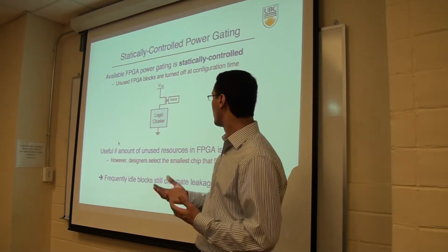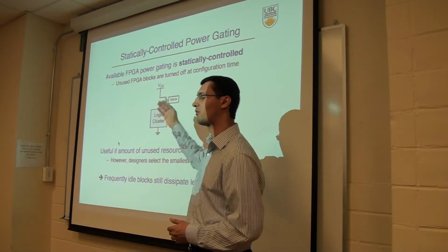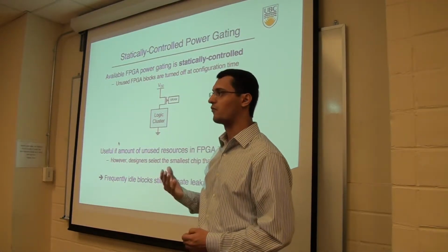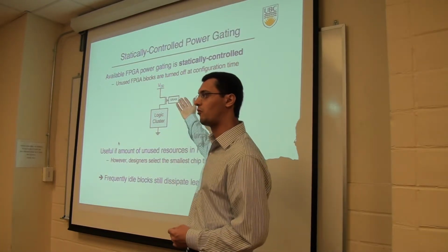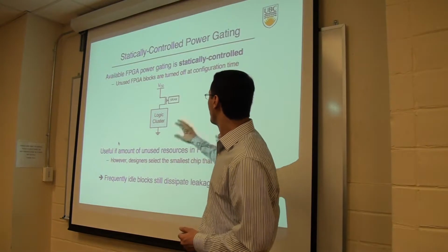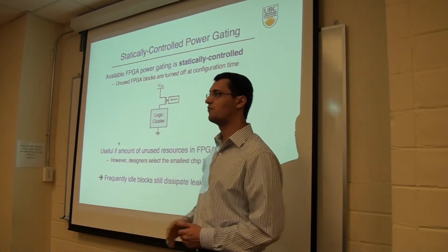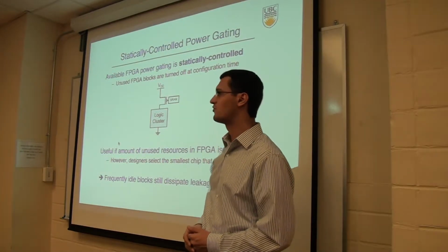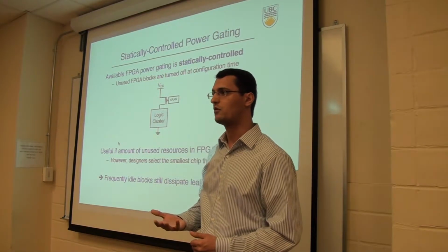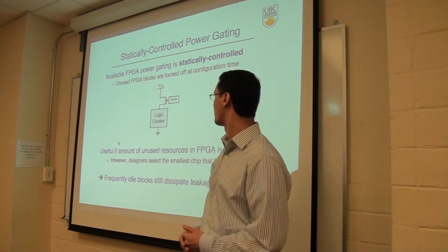And there are some area and performance trade-offs here because the size of this PMOS sleep transistor determines how much area overhead you have, what the performance degradation is because of the voltage drop through this PMOS transistor, and so on. What I mean by statically controlled is that using this S1 configuration bit, you can configure this PMOS transistor at configuration time, whether the logic cluster will be in sleep mode for low power or in active mode, which basically consumes power.